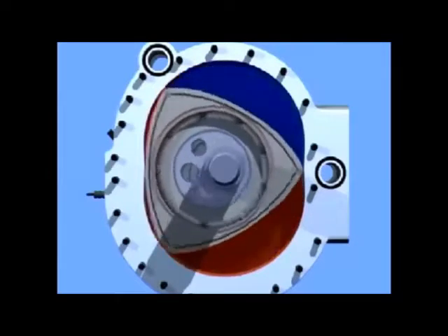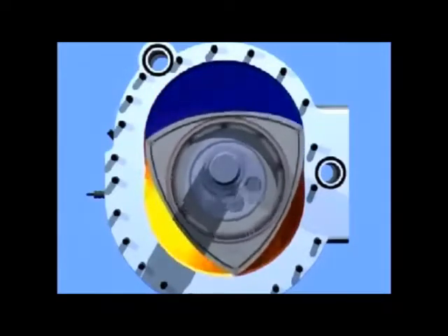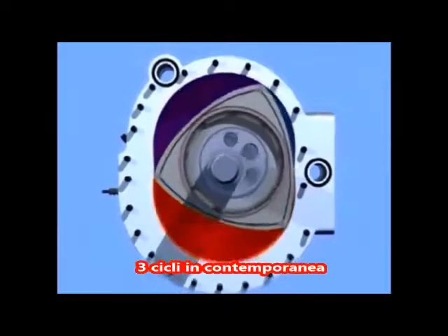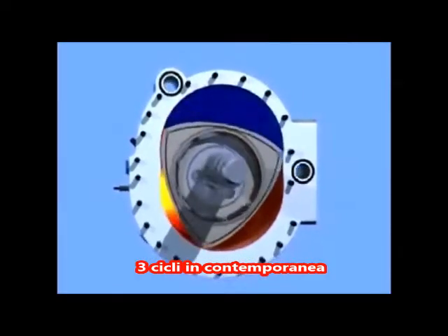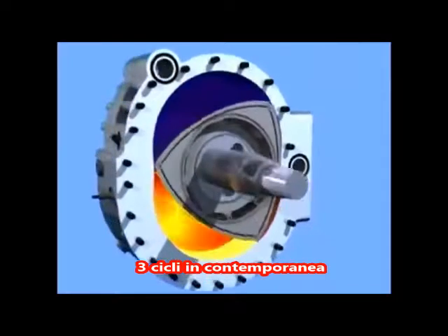The special shape of the rotor and housing creates 3 combustion chambers. This means that a single rotor Wankel engine is comparable to a 3-cylinder piston engine.